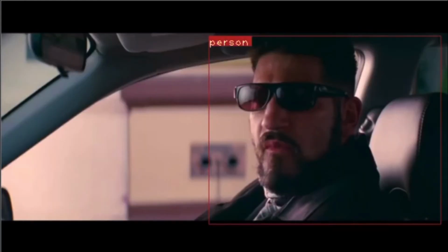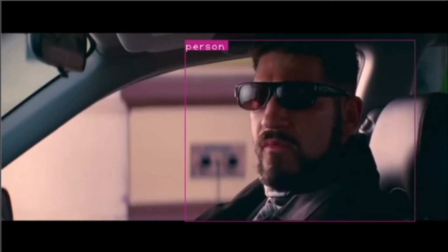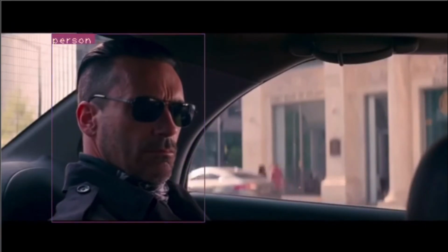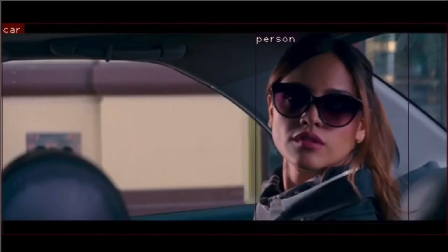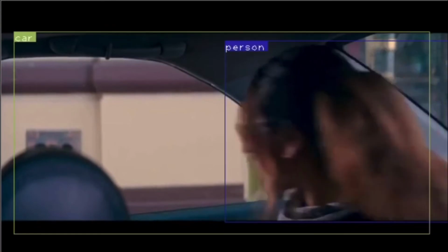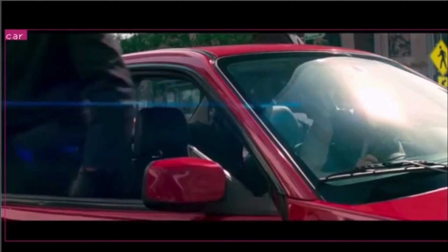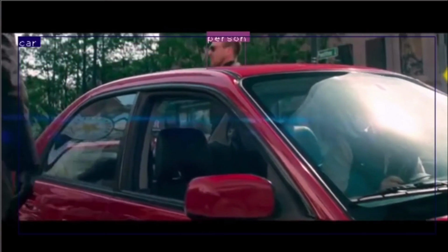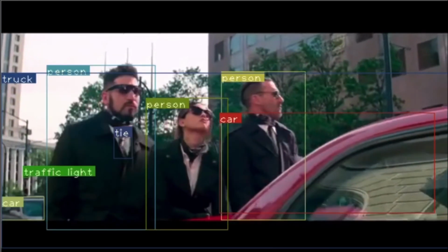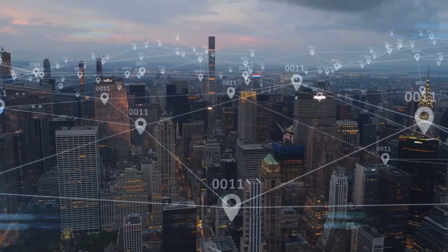When the video streaming reaches the server, the YOLO algorithm is used to analyze the video searching for any obstacle and send the feedback to the drone. We have trained the YOLO model to detect the obstacles as well as guess the distance between the drone and any obstacle, which helped the drone in taking the suitable action. Upon receiving the feedback from the server, the drone begins immediately to take precautionary actions to avoid possible collisions. By achieving this, we enable everything to be connected with less and less human interaction.